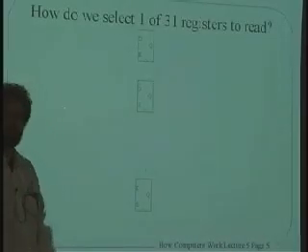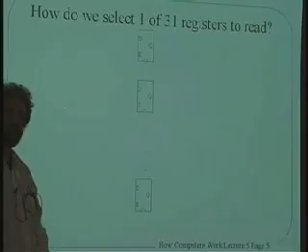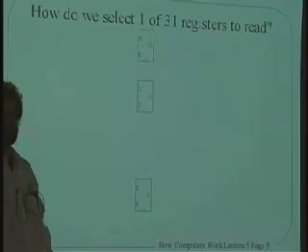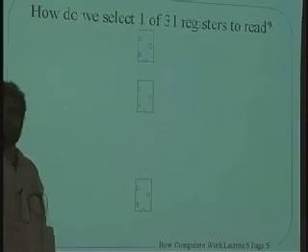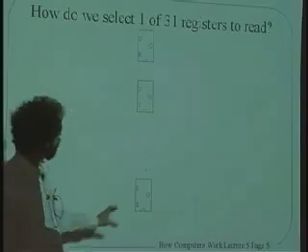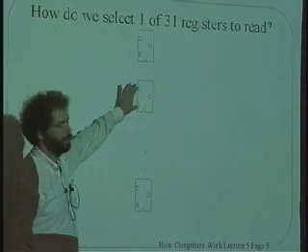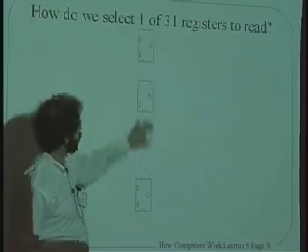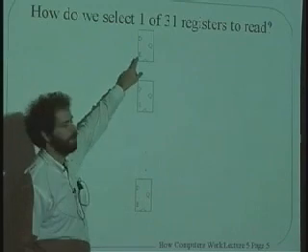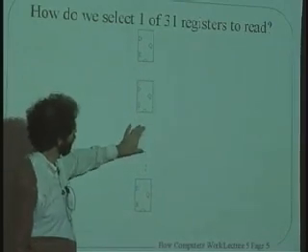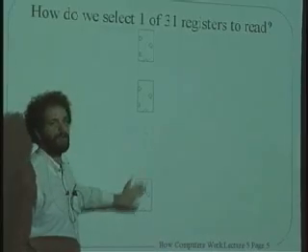Well, we have this register file. And the register file, if you remember, had 32 registers in it, of which the last one is going to be all 0. So there's really only 31 of them. So I could take 31 of these 32-bit registers over here, and arrange them in a row, and say, okay, this one over here is going to be R0, and this one's going to be R1, and the next one down here, R2, R3, all the way down to R30.